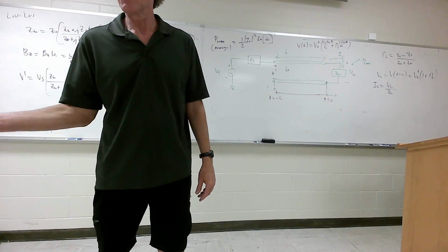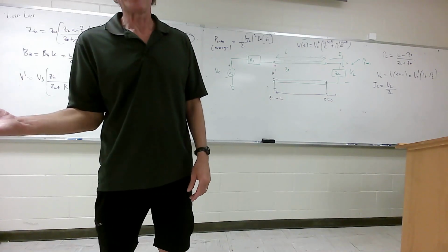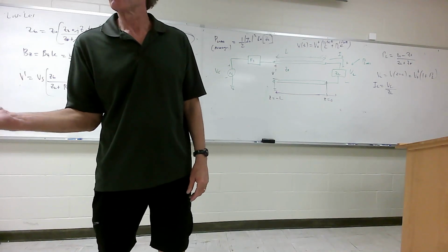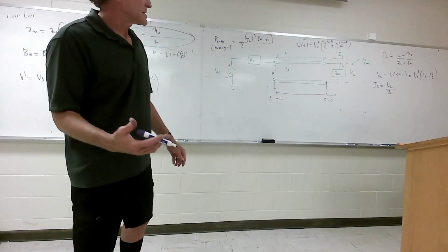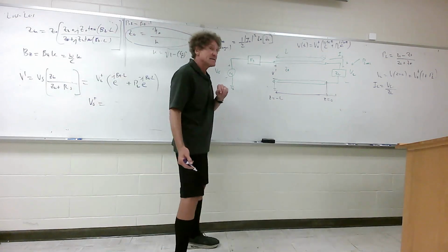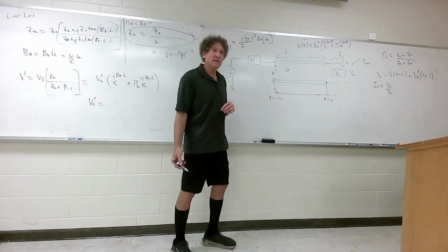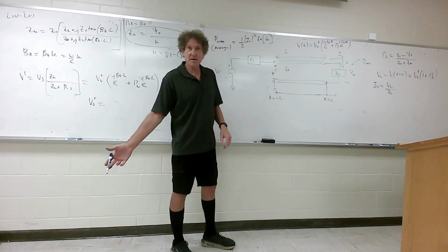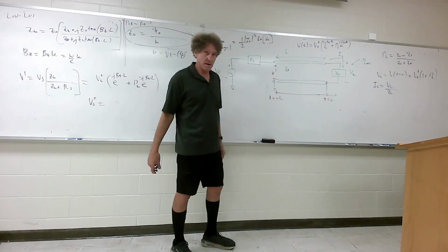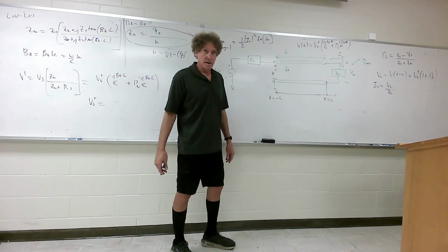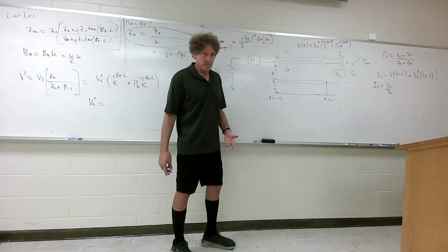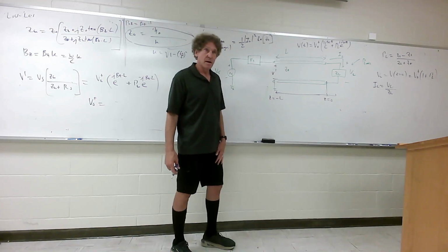Do y'all follow me, class? You know what I'm talking about? An inductor or capacitor does not dissipate power, only a resistor. And this is the easy way to do it. IL is easy to get. Usually the load would be like 50 ohms plus J 20 ohms. It's only the 50 ohms you're worried about. You all with me? You good with that? And that will work.